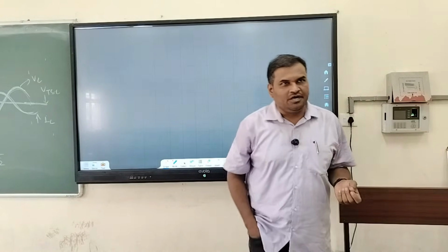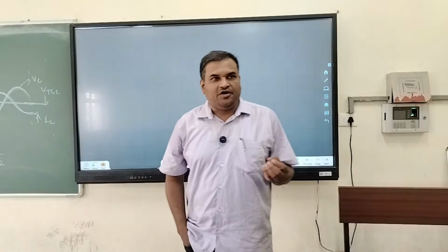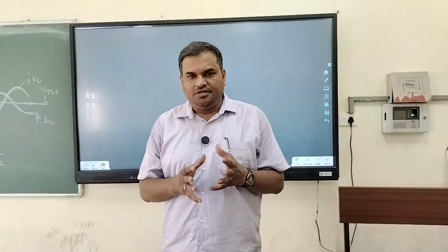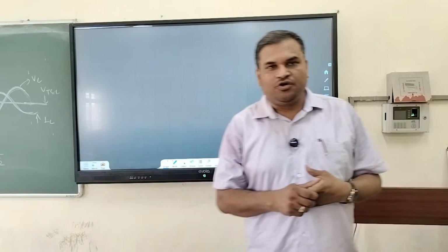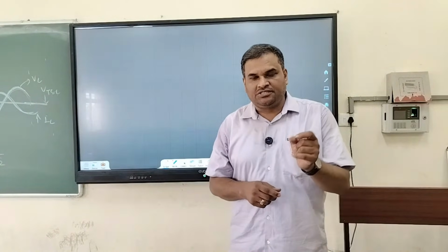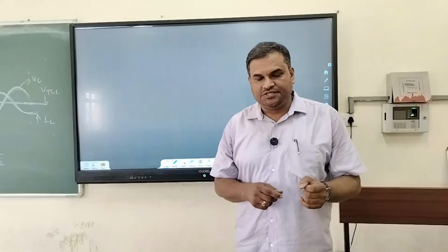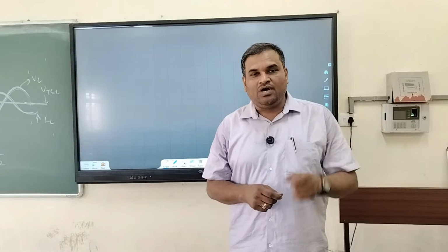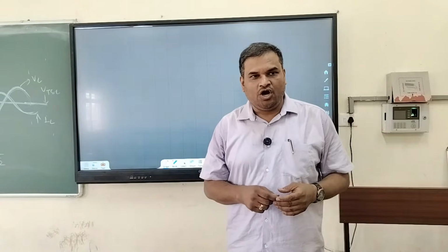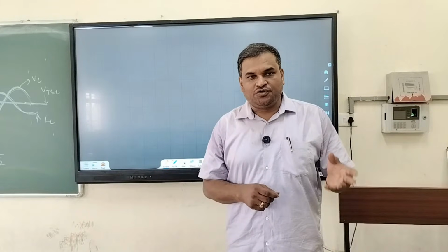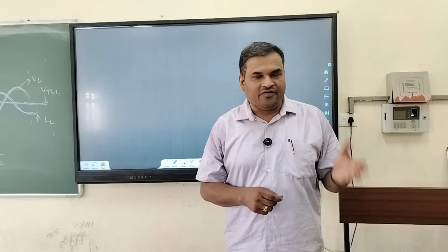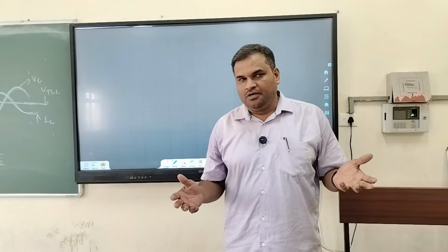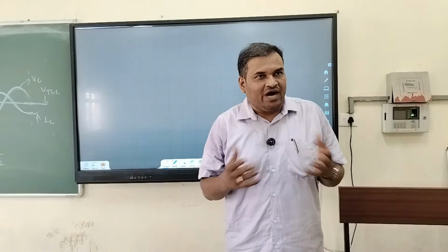We are going to start today the effect of harmonics on the induction motor drive. We are giving a three-phase supply to the induction motor, at a frequency of 50 Hz. If we give the supply to the induction motor through a voltage source inverter or a three-phase inverter, the input voltage will not be sinusoidal; rather it will be a square wave kind of thing, and these square waves generate a lot of harmonics.